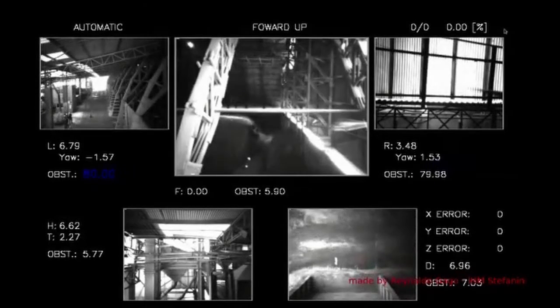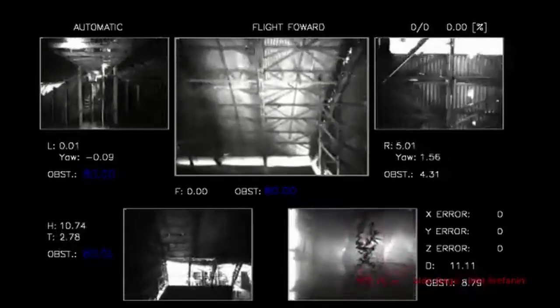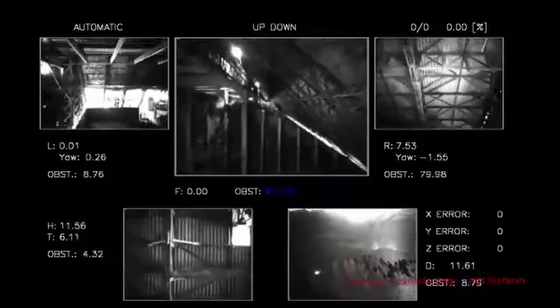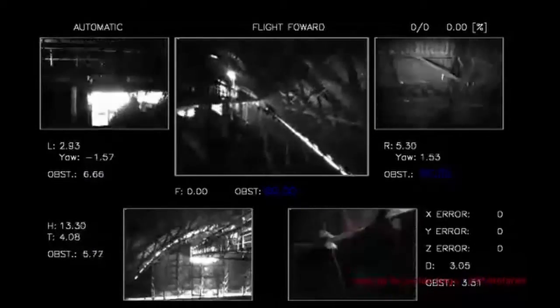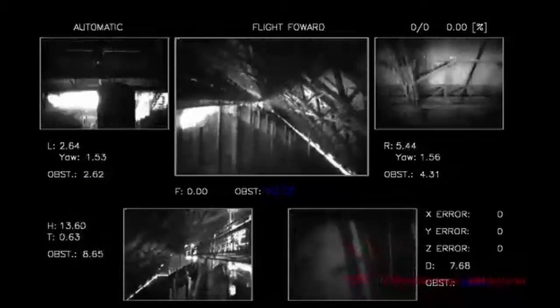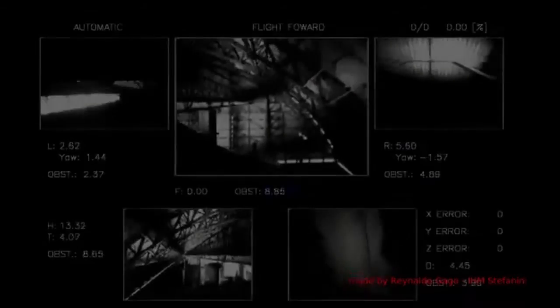Here is our innovative experience that we created to take accurate volume measurements of a hazardous pile of fertilizers in an indoor warehouse. Our solution involved building and executing an autonomous drone flight path to learn the indoor layout of the warehouse, with collision avoidance between struts and beams in place, capture images of the pile, and offline analyze the point cloud data to get the accurate volume information.